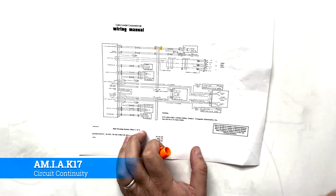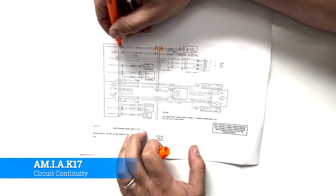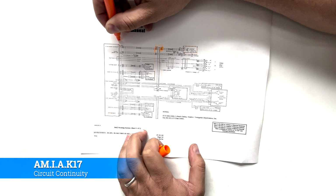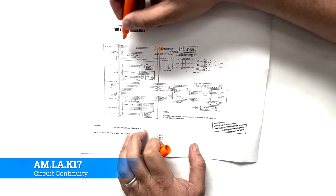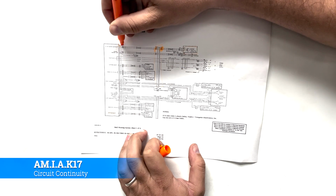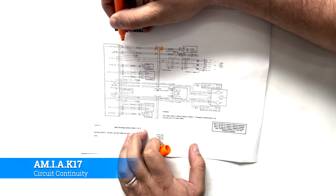So let's do a thing. Let's ring through it. We're going to go over here to pin G, and we're going to go to ground. All right, kind of did that backwards, but yeah. So we're going to ground that out. Take the connector off, put a pin on, or put our lead onto G, and then clip it off to a grounding point somewhere on the aircraft.